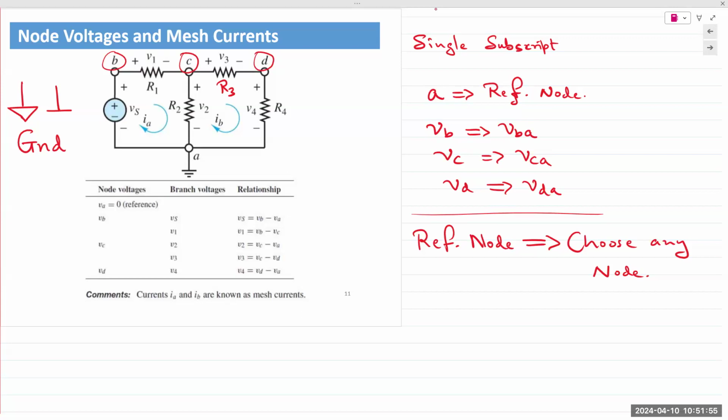In your analysis, again, we are trying to generate equations for the purposes of analysis. So equations will have unknown variables. In this case, the unknown variables are the node voltages. So the fewer unknowns we have, the easier our analysis. Make sense? In this case, we have 4 nodes, so there are 4 unknown variables.